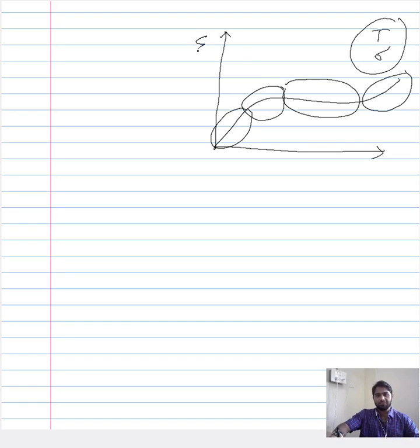So these are the different stages that the conventional representation of the creep behavior gives us. And of course, we have seen that similar behavior is also observed in the different forms of representing the creep behavior. But this is how we can categorize the creep curve into different stages. Now we have seen that the usual way couples the instantaneous and the transient stages, meaning stage 1 is usually the combination of instantaneous creep and the transient creep.